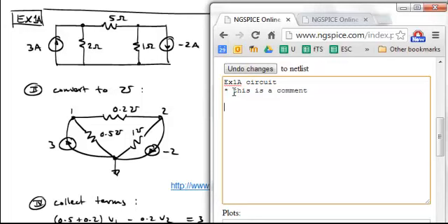So let's begin by inputting the resistors. R1, okay? The way you enter any element is you first give it a reference designator, in this case R1. SPICE knows what kind of element you're actually meaning to input by the first letter. So R is resistor, and then you could call it R apple, R23, R1, doesn't matter, but R is what tells SPICE that it is a resistor. Then we list which nodes it connects to, and we go from the positive node, which is 1 in this case, by my choice, to node 0.